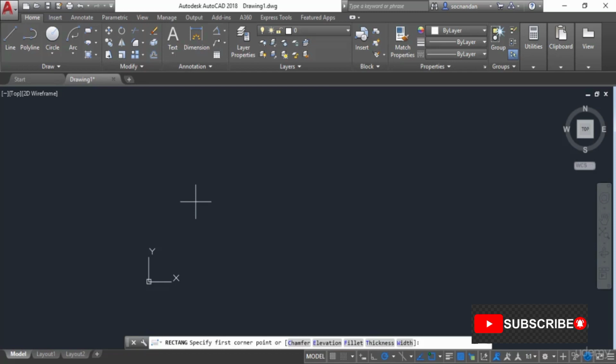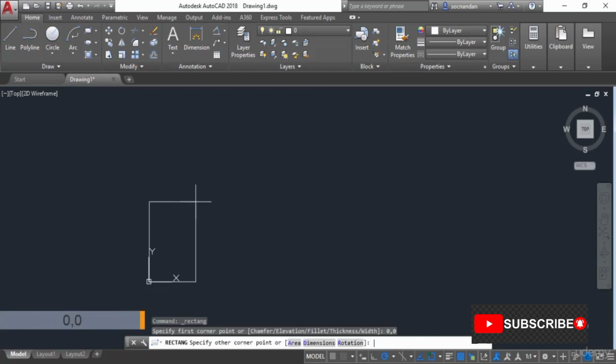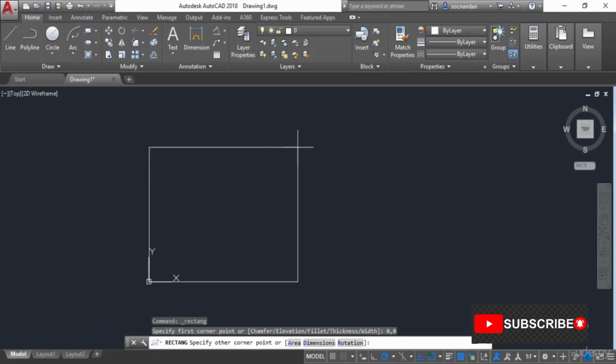Now select the rectangle tool, and now you need to specify the first point for making the rectangle, and you can specify the first point as 0, 0. That will be the origin in this case, and you can see that the rectangle starts from the first point at origin. Now look at the cursor, which is at this vertex of the rectangle, and now when you look at the command line you will see that it's prompting you to specify the other corner point, and that is this corner point on which we have our cursor right now. So all you need to do is enter the coordinates of this point. So let's say that we want to make a rectangle with length 10 and width 5.